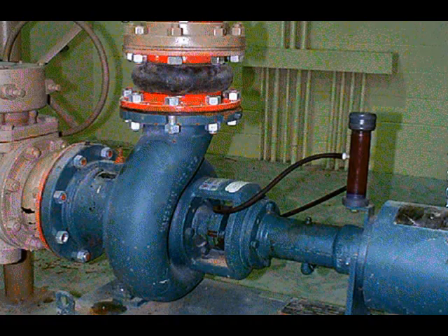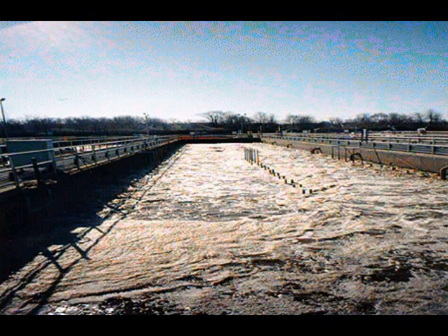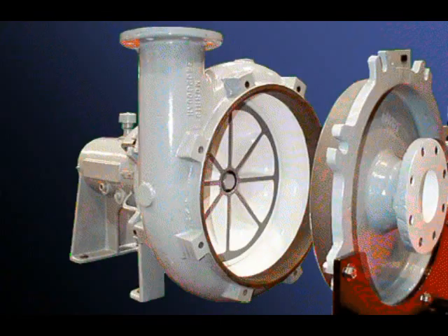Centrifugal pumps are the most versatile and have many uses around the plant. Centrifugal pumps are used for pumping all wastewater flows and all thin sludges. For thicker sludges, recessed impeller centrifugal pumps may be used. Pumping efficiency is reduced, but recessed impeller centrifugal pumps are more resistant to clogging than other centrifugal pumps.